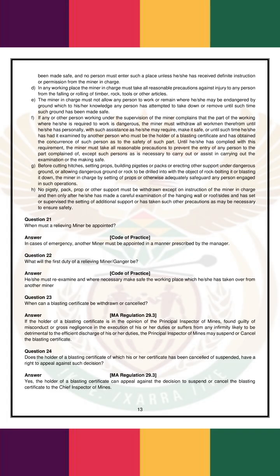Respond to safety complaints. Stop work in unsafe areas and ensure safety through inspections or by certified personnel. 7. Safeguard dangerous operations. Ensure proper support and precautions during risky activities, e.g., drilling, blasting. 8. Withdraw support safely. Only remove support structures after inspecting and adding necessary precautions.